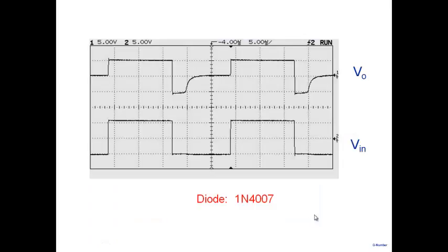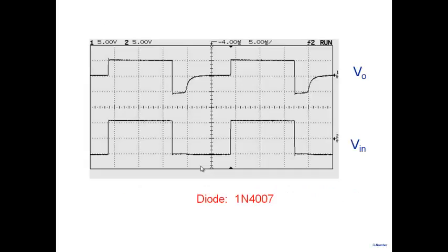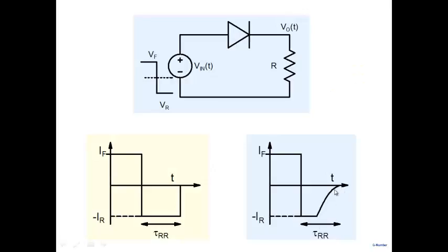Okay, let me show you. This is from our 380 lab, 1N4007. The TAs and other students may remember doing this experiment. Look at this diode reverse recovery. This is the forward voltage here, and we immediately switch it to reverse voltage, and look at how the diode is switching off. There's a constant part, and then there is a well-defined region here, a fairly large region, which is not predicted by our normal quasi-static model.